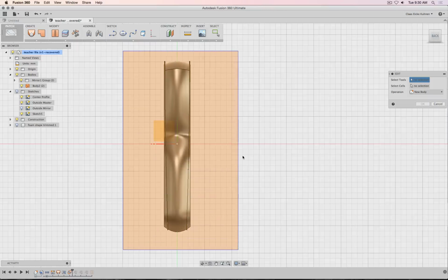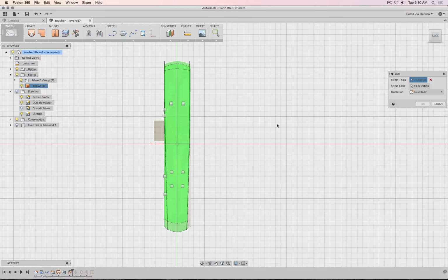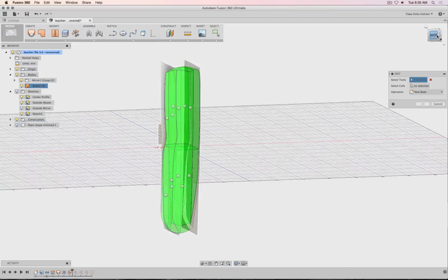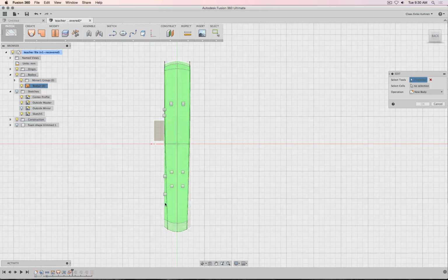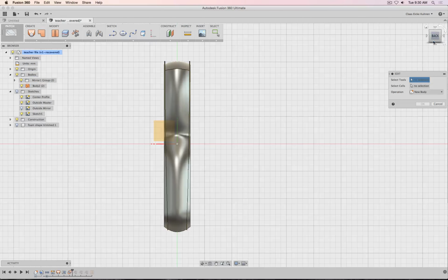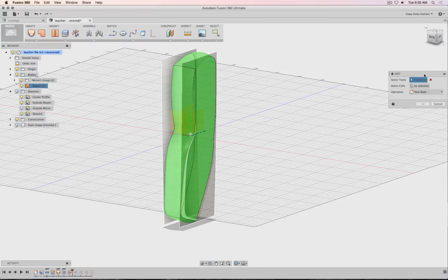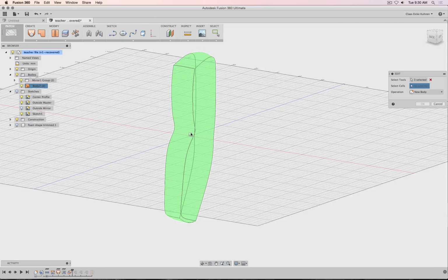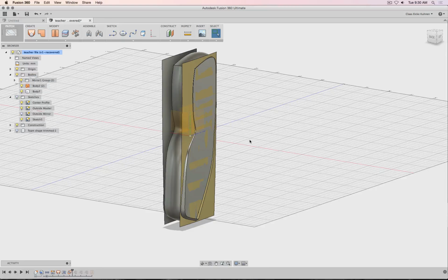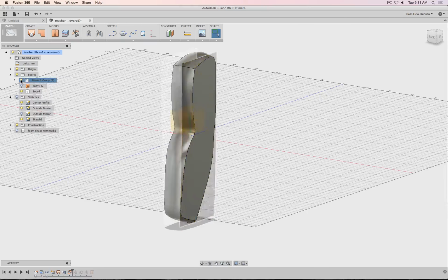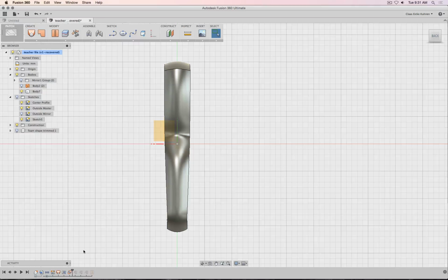So if I drag over everything, I get all those cells. Okay, so I guess then, oh, see, there's this additional cell, and there are some additional cells. So it includes that. Okay, so it's really important, as you can see, how actually you click on those surfaces, and then select your cell, and you're done. So basically, as you can see, that's the same result with one command as doing 3 stitches, 3 trims, and then a stitch.